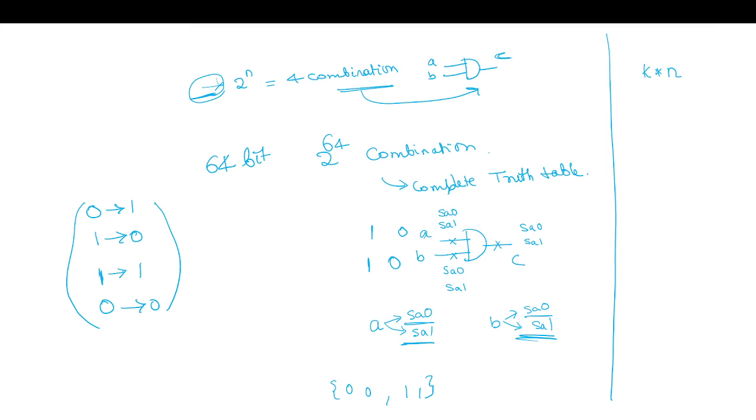So this will be each and every node having one fault at a time. Now if we have multiple faults, then we have various combinations of faults. Either two nodes can be stuck at 0, or one node can be stuck at 0 and another stuck at 1.